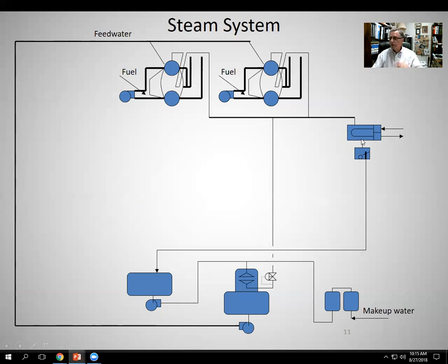So the steam would condense inside the heat exchanger. The liquid would flow down into this device, which would be a steam trap. It's kind of like a little float mechanism we're showing in there. So when this fills with liquid condensate, it would open and the condensate would be passed down this line back to a condensate return tank, whereby it would be pumped into this, a deaerator.